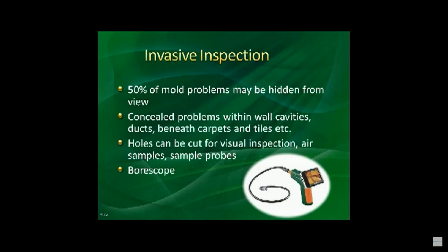There are invasive inspection techniques. You could use a borescope, looking through a receptacle cover behind the wall. In certain areas, you may lift a ceiling tile and use that. The new types of borescopes have come a long way, and they have video and picture capabilities. As you see, this is actually a BR200. You can take that screen off, set it aside while you're using the scope, and video your inspection.